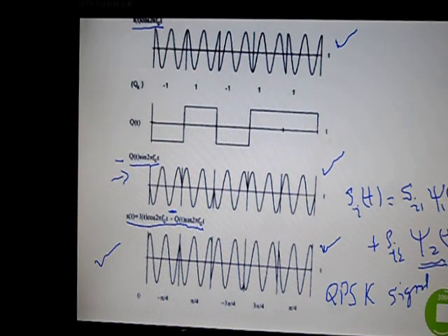Now just concentrate on the first period. From the I channel you have this waveform, from the Q channel you have this waveform. When you add these two, you get the third waveform, shown here. Now you can see the phase difference. The phase angle here is minus pi by 4, which is the result of addition of these two waveforms.